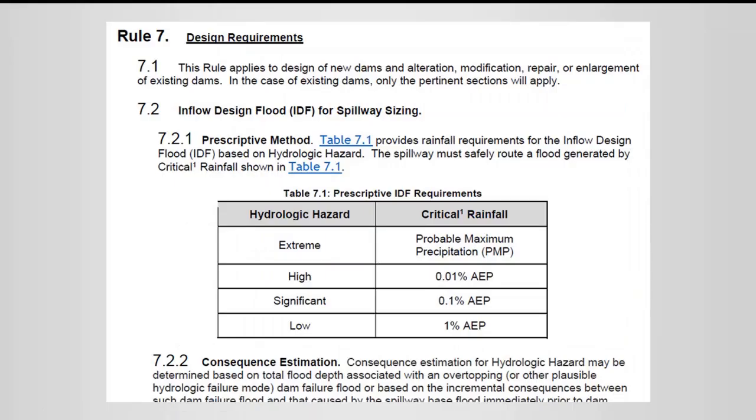Okay, so now let's go to the hydrologic design process. I know this is the part that everyone wants to go to. We're design engineers, we want to design and build things, and we kind of automatically jump to the inflow design flood. But that first step for working on any existing dams, evaluating hydrologic adequacy by hydrologic risk analysis, is critical. And I want to reiterate that the determination of hydrologic adequacy comes from the State Engineer under Rule 5 and statute.